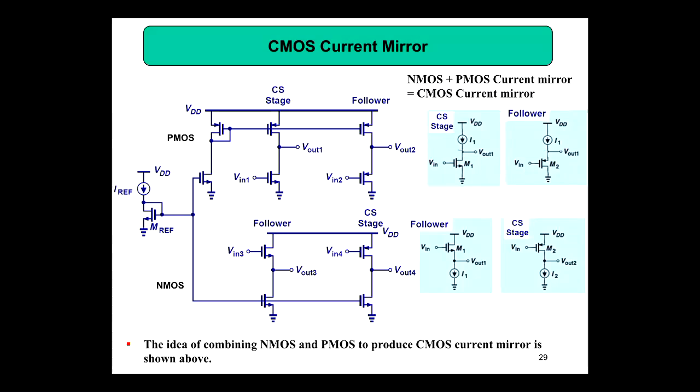So in this section, what we studied is current source, and how to increase the impedance of the current source. We came up with the idea of the cascode stage. Then we studied a cascode amplifier. Then we studied the importance of the current mirror.